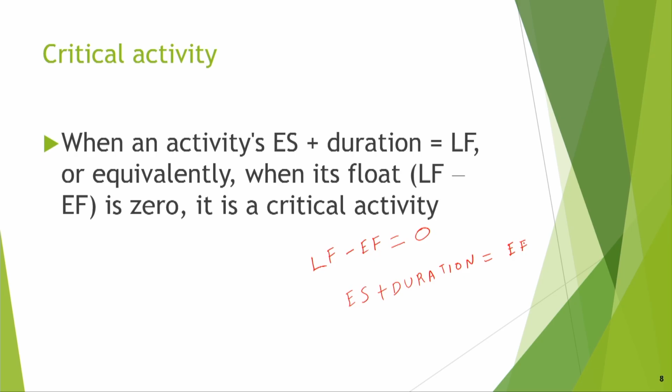ES plus duration is equal to EF. So, if you have LF minus EF equal to 0, then it is a critical activity. Therefore, I have said that this equal to LF becomes the condition for a critical activity. So, it is just algebra.